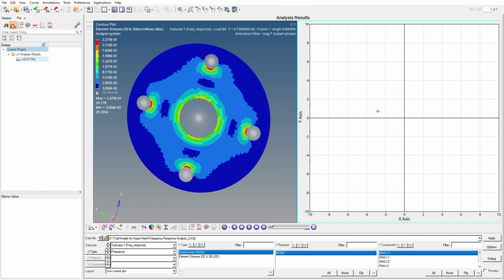To visualize the results in this, what we basically do is we observe the behavior of the part, object, node or element in graphical format. Fine. So for this also you will load the H3D file. Okay. So the x-axis I have kept as frequency, y-axis you can select either displacement or element stresses. Next we have to select the node number. So we have N1, N2, N3, N4, N5, everything.